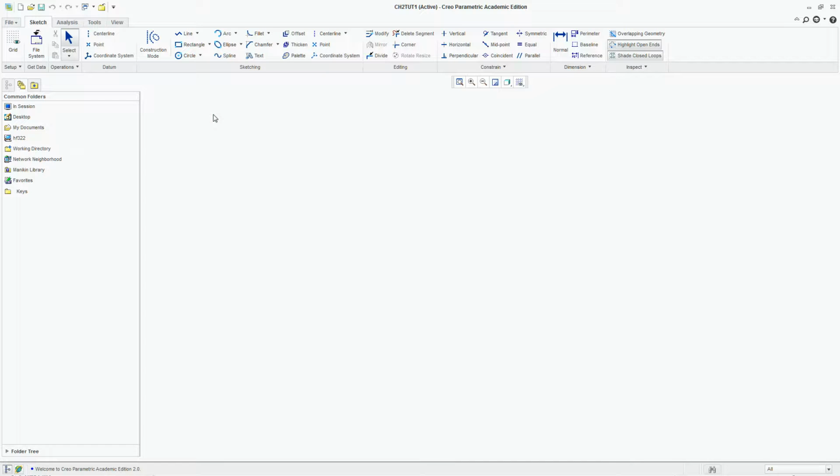So what I'm going to do in this situation is I'm first going to draw my circle. And I'm just going to draw a single circle, and then I'm going to end the circle command. And I can see that that's coming up with a diameter of 3.69. Well, the outside radius on tutorial 1 needs to be a radius of 4, so I need to go ahead and make the diameter of this 8. So now I have my scale reference that I can use to draw the rest of this object.